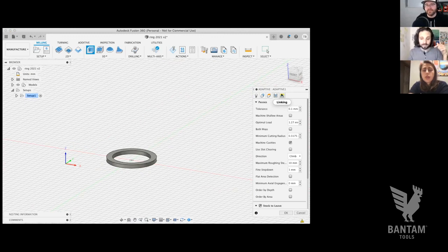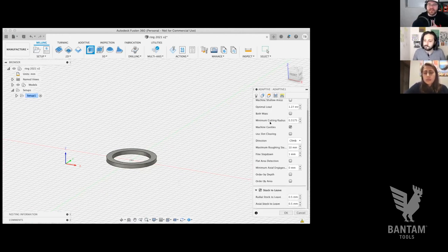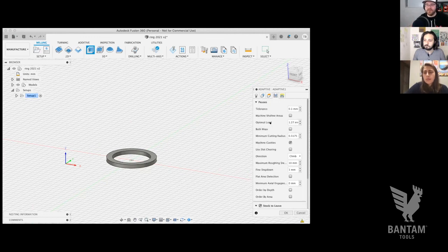And it seemed like it was just erring too much on the side of being too cautious. It was being too tenuous. This is where I might be able to mess with that setting. Exactly. That would be step over, which is another term, but basically how much of the width of the tool is engaging. So, 100% of the tool, or part of the tool.